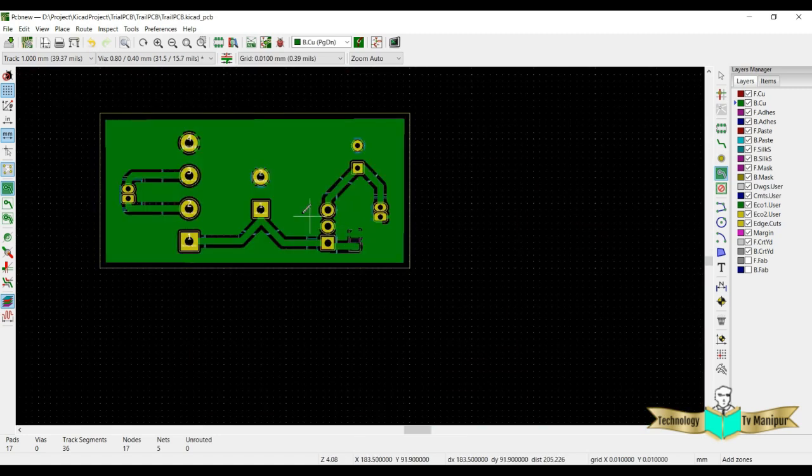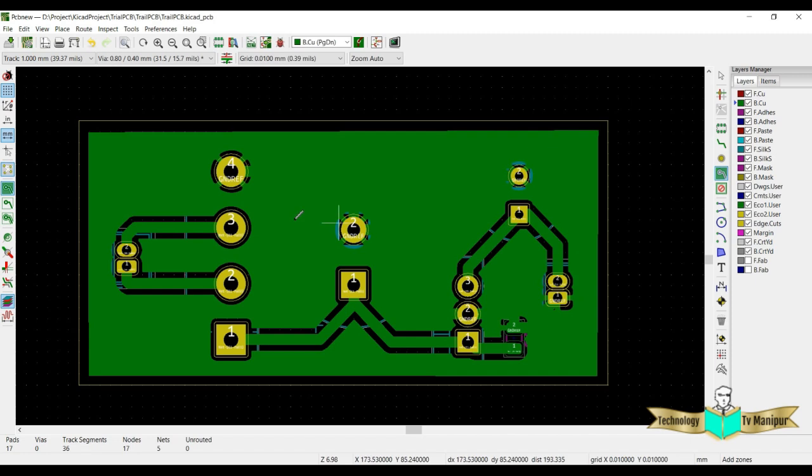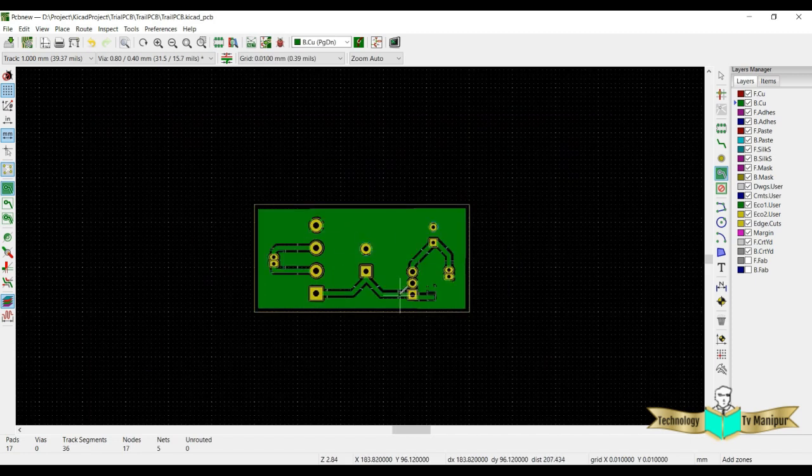So here, you get a layer now. The remaining part is filled with the ground copper, but wherever it is required, it is etched out, so the copper is not fully shorted, okay. So all the ground part will be connected automatically by adding this fill.